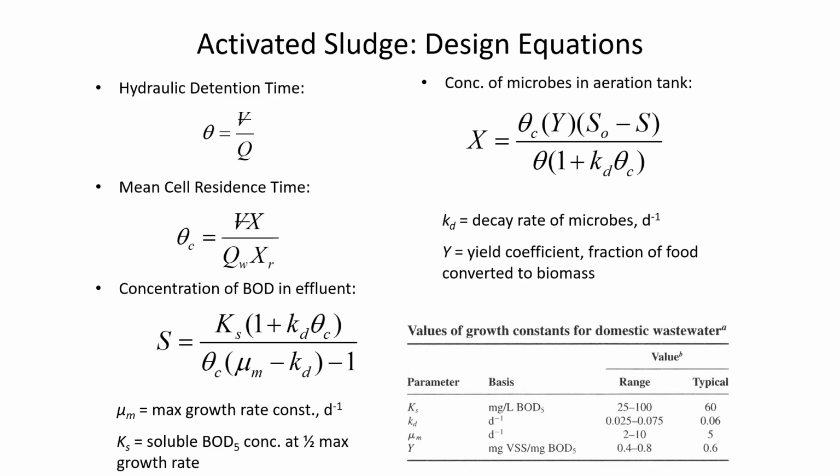The difference being that there's some amount of the energy that they're consuming which is used for cellular respiration. It's just the energy they consume for metabolism, and then some of the energy that they consume goes into new cells that are growing. Because remember, they're going through the process of binary fission. They're dividing from one microorganism to two, 2 to 4, 4 to 8. And that binary fission leads to additional mass, and so the yield accounts for that.